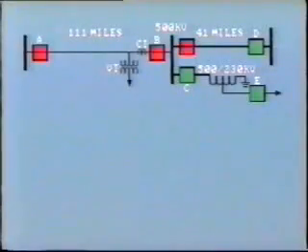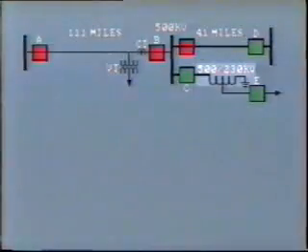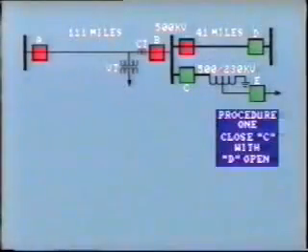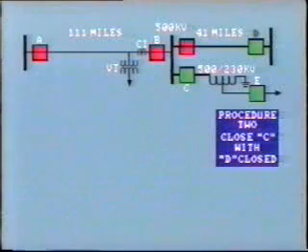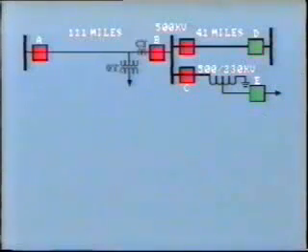We're considering 2 different switching procedures for energizing this 500 kV, 230 kV transformer. In the first procedure, breaker C is closed to energize the transformer, with breaker D at the remote terminal open. In the second procedure, breaker D is closed first before energizing the transformer with breaker C. The oscillograph has recorded voltages and currents on the line side of breaker B at the transformer substation.